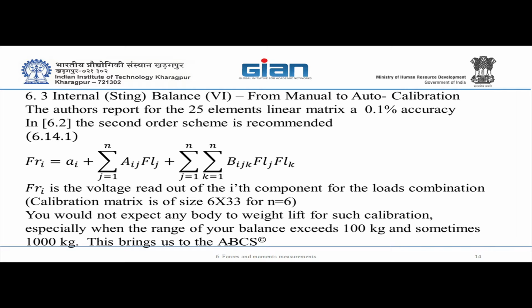I mean, no, you have to make it. You have to work on the balance itself. You have to again take the balance and exert that map of loads that were running in the test, acquire those points by exerting those loads in the machine, calibrate and get new coefficients. And then you can recalculate your results from the tunnel with the new calibration.